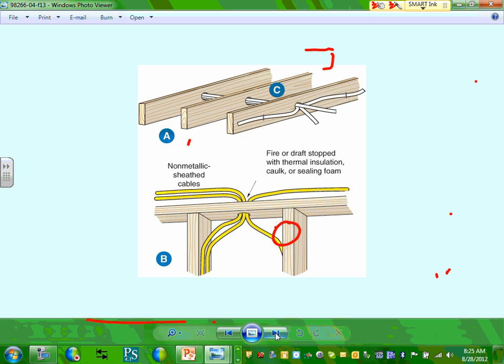Bringing the conductors down into the panel, you drill a hole. If you caulk this hole, which you should, you have to derate. Then it gets into the derating based on exactly how many conductors. So 1, 2, 3, three cables, let's say each one is 12/3.